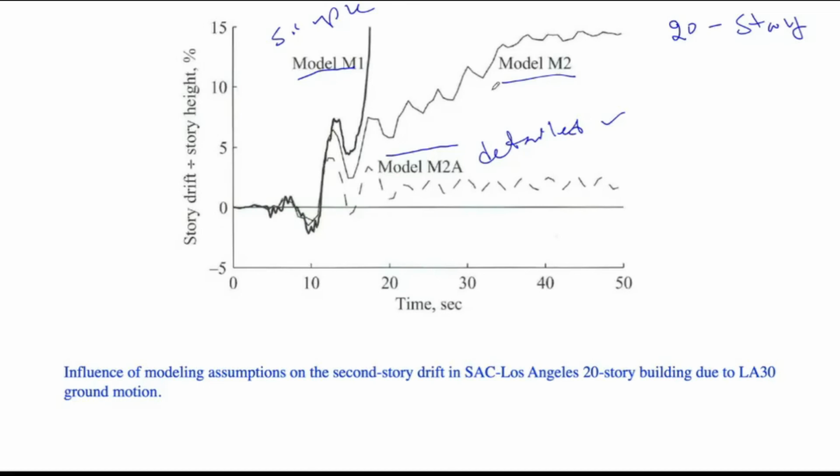So with this, sometimes when we design a structure, we always assume that the beams are rectangular. But when we look at the structure, beams are casted monolithically with the slab. So in that case, for the assessment, it will be very important to consider this as a T-beam rather than just as a rectangular beam.